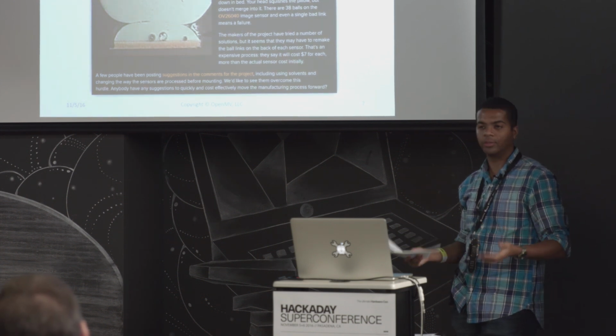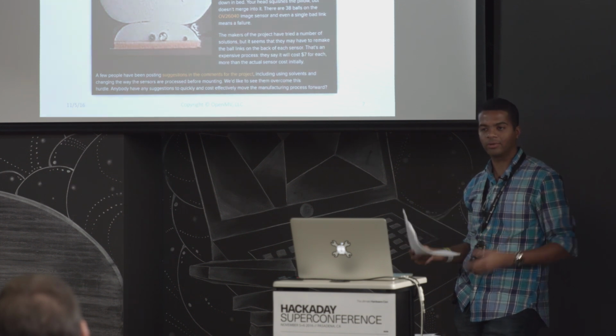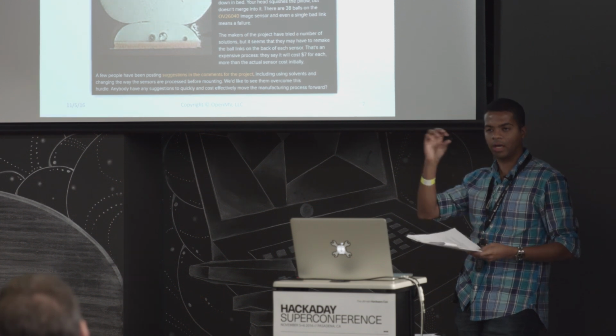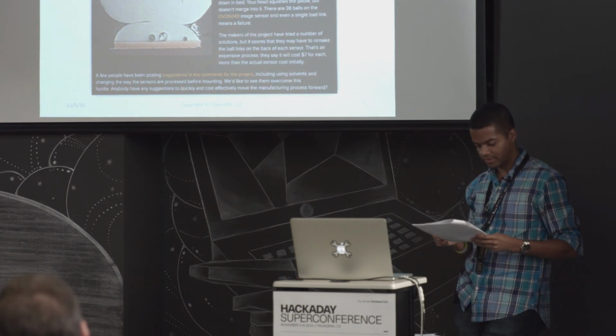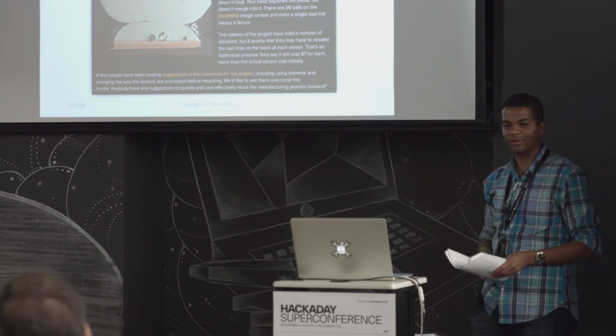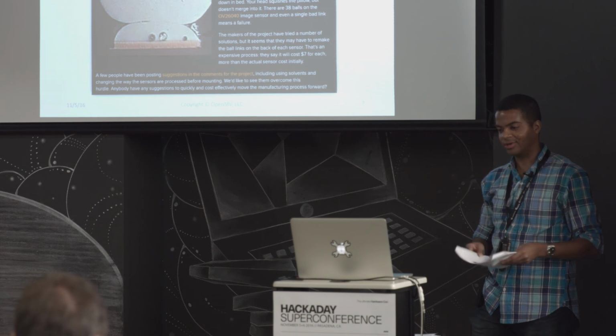For our own personal production, we were just using a lot of heat with a hot air gun, and that would eventually get it to work. But that also risked cracking the camera chip because it has a little glass panel on the top of it. So there is a difference, of course, between building one unit when you're prototyping and going to mass production and building a huge amount.